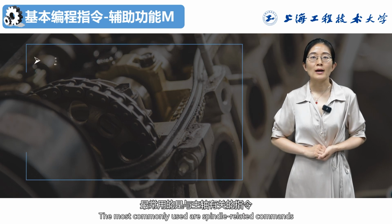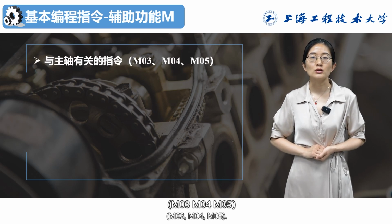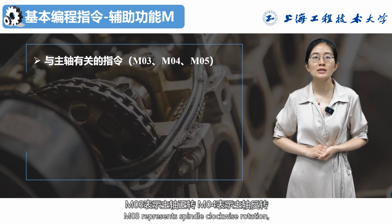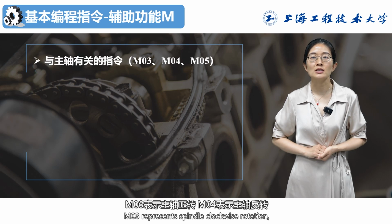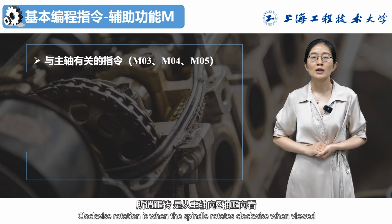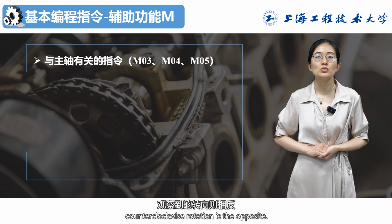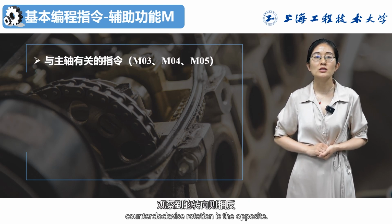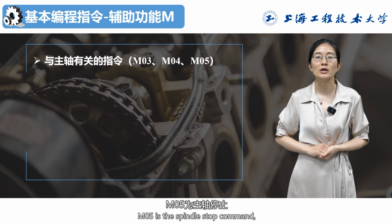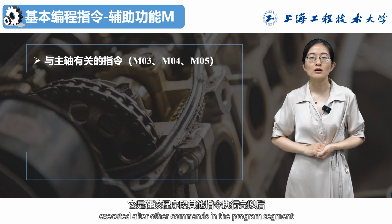The most commonly used are spindle-related commands: M03, M04, M05. M03 represents spindle clockwise rotation, and M04 represents spindle counterclockwise rotation. Clockwise rotation is when the spindle rotates clockwise when viewed from the positive z-axis direction. Counterclockwise rotation is the opposite. M05 is a spindle stop command, executed after other commands in the program segment have been completed.